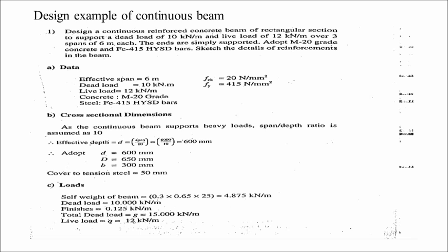This is the effective depth. Adopt effective depth 600, overall depth 650 and width 300. Cover to tension steel is 50.